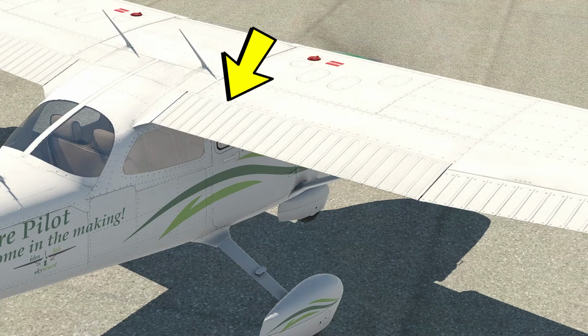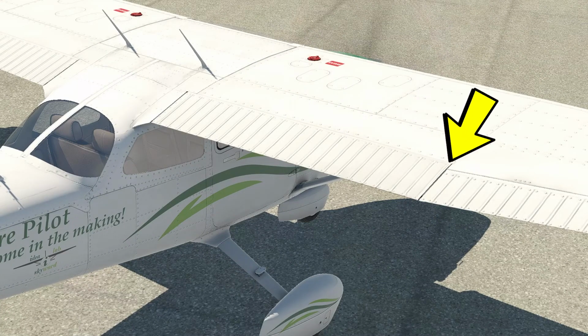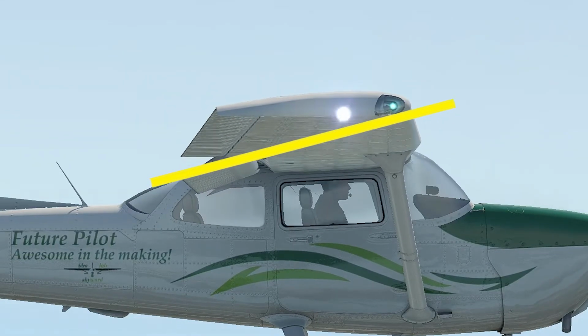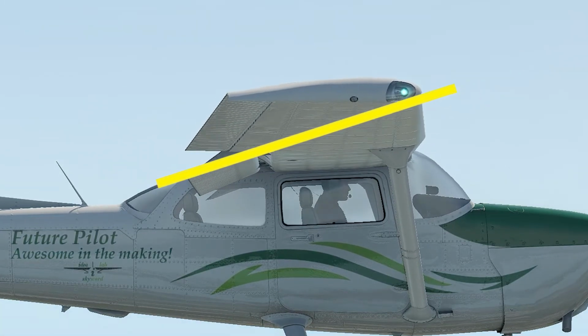The flaps are control surfaces on the inboard part of the wing's trailing edge and work together to increase lift by changing the angle of attack. Lowering flaps causes the wing chord to angle higher without the aircraft's pitch changing. You'll see a good description of this later.